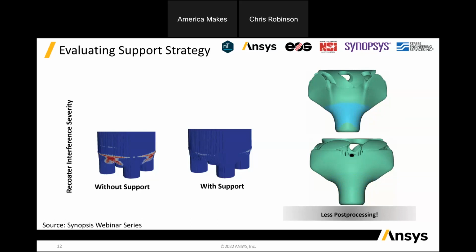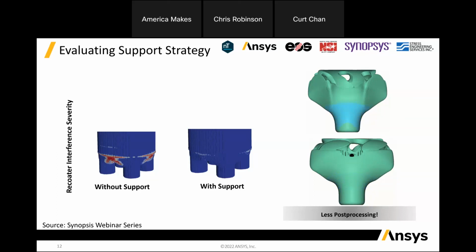But one of the key things that I really like about simulation is that it allows you to go even deeper than just finding one solution to a problem. You can start to really explore what's going to happen with different solutions for solving that problem. So for instance, on the right, instead of adding supports, you can change the geometry there, which would lead to less post-processing. You can just quickly look at it and see that there are some small little areas that are stemming from where that blade crash, the recoater interference, may occur.